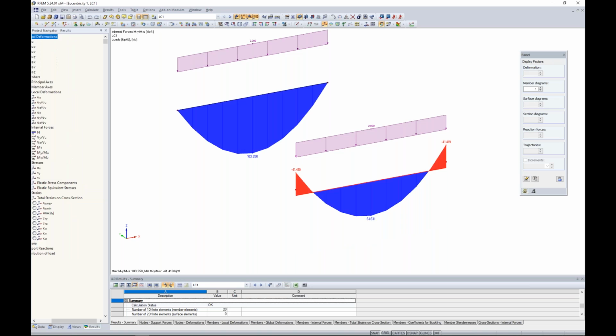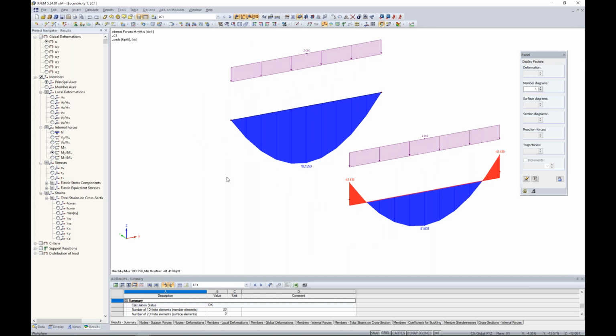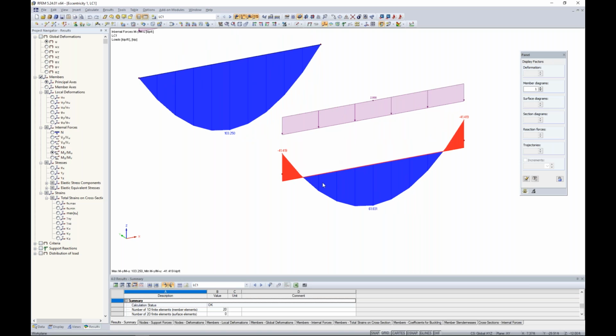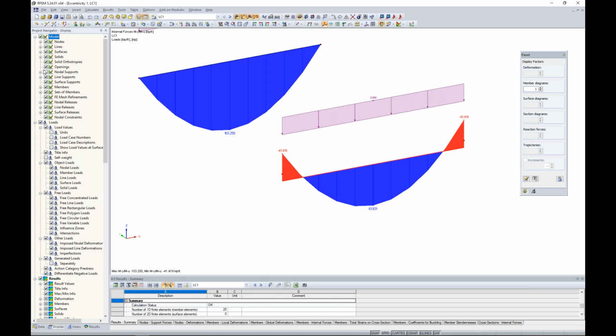We'll immediately start off with the moment diagram. So, a simply supported beam, we take a look at our first example here. This is exactly as we'd expect for our moment diagram, peak moment right here at the center. But as we transition into those nodal supports, which are a pin-roller type situation, we expect no moment. Well, by introducing this eccentricity here to drop the top of steel down to where our nodal support is, we now have a negative bending moment here due to those rigid elements at the end. Our peak moment here in the center is almost half of what we're seeing with our original beam element.